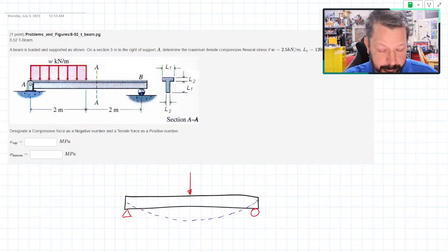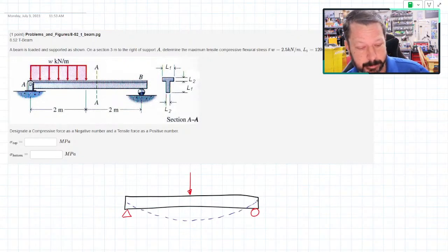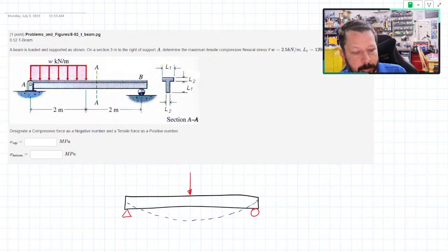But if we were to envision it bending this much, and again, they don't bend this much in practice, but we're having to exaggerate it so you can mentally see it. In fact, that's one thing that I do whenever I'm trying to figure out how these mechanisms and beams and linkages and whatever the machine might be made of, whenever I try to envision what it's going to do as far as failure goes, I envision it not as metal, but as a rubbery substance, so it's easy to bend and deform and all of that.